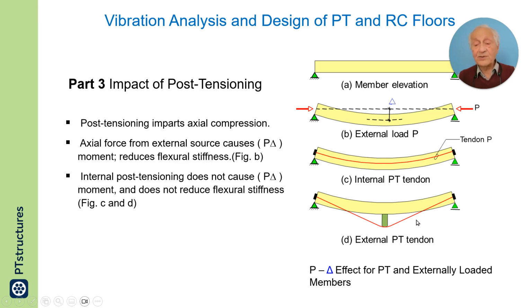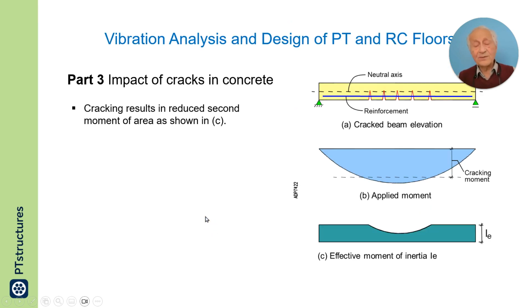Likewise, even if it is externally post-tensioned, when the member goes down, the eccentricity of this force with respect to the centroid remains unchanged. For that reason, you can have precast, pre-stressed piles that are 100 feet, 30 meters or so, and they are lifted by a crane to go to the place of installation and bend, but they do not break because of the pre-compression,